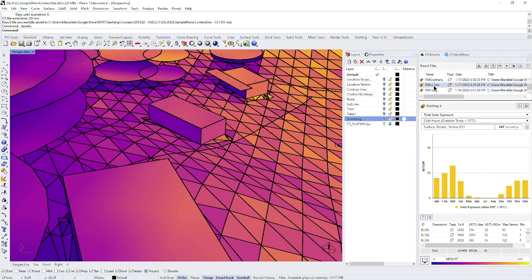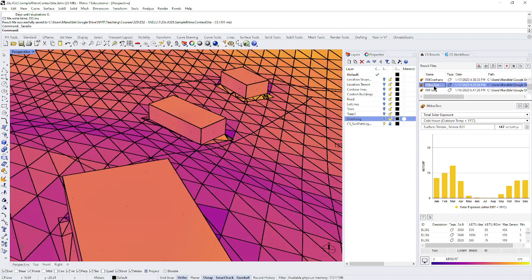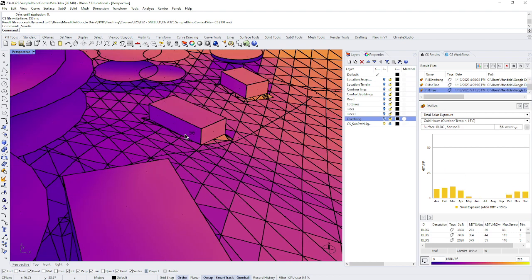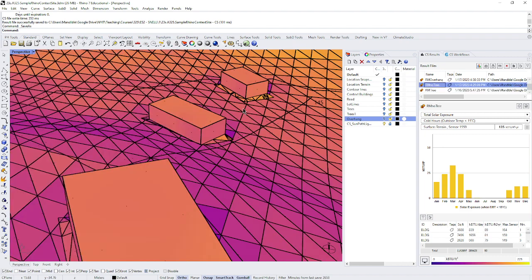Now, if I get rid of the trees, let's say I was going to cut them all down, this exact same sensor has 133 kBTUs per square foot per year, so over double on this space with or without the trees on this site. Now that's really important information to have, and I can get it really quickly. This model is very easy to make, and I can make it quickly. So powerful, 50 to 133.